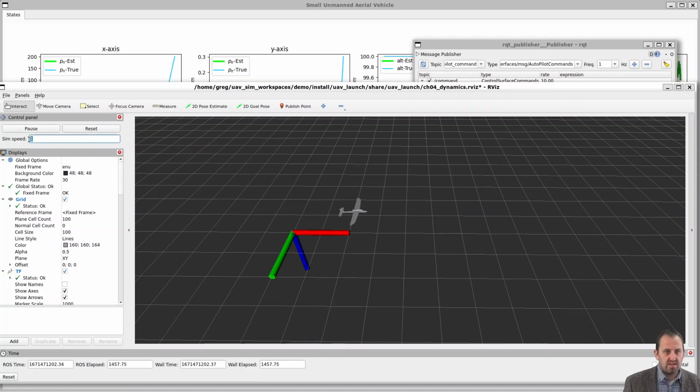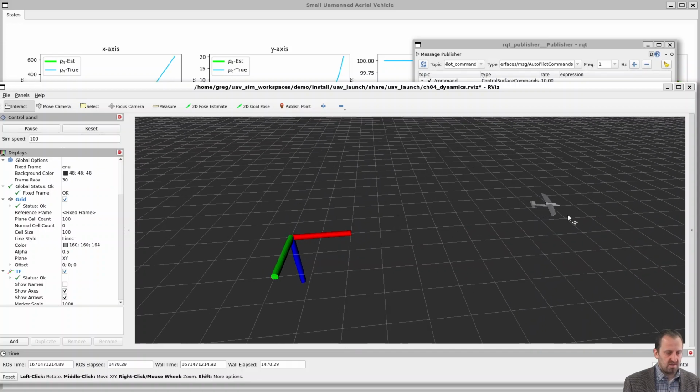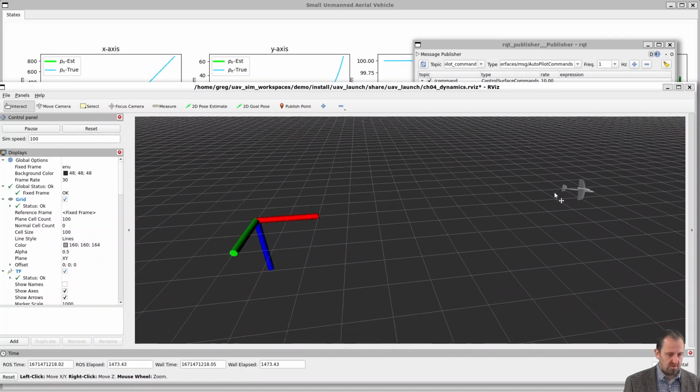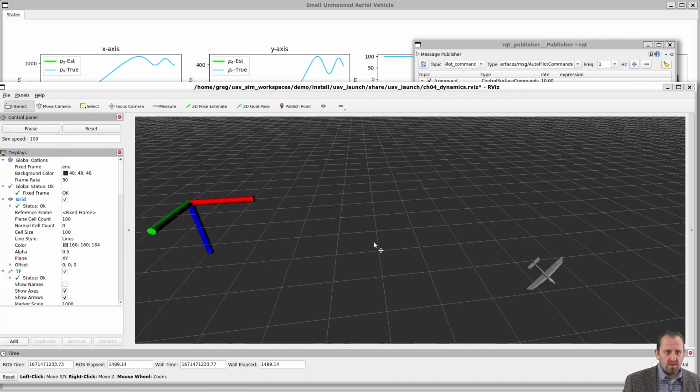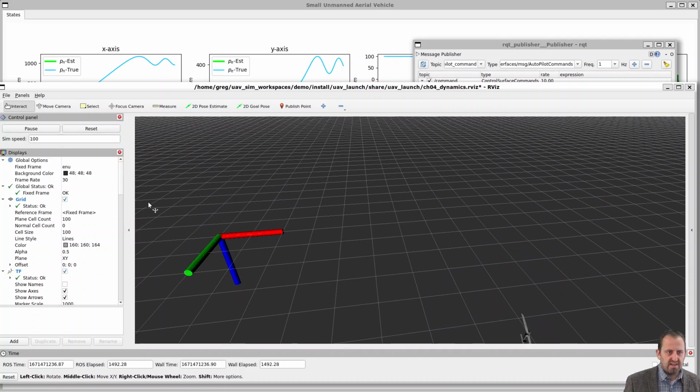Now, we do have errors in our dynamics when we're calculating this. Let's see if we speed this up. Eventually we'll see that our aircraft starts to, oops, wrong button, shift off of that nominal straight line trajectory. And remember, each one of these squares is 100 meters, so it took a while to shift off, and now we're doing a nosedive, right? So the trim trajectory is really nice in that it allows us to define a trajectory which the aircraft, left uncontrolled, performs fairly well for a little bit. So we'll pause that and reset our motion.